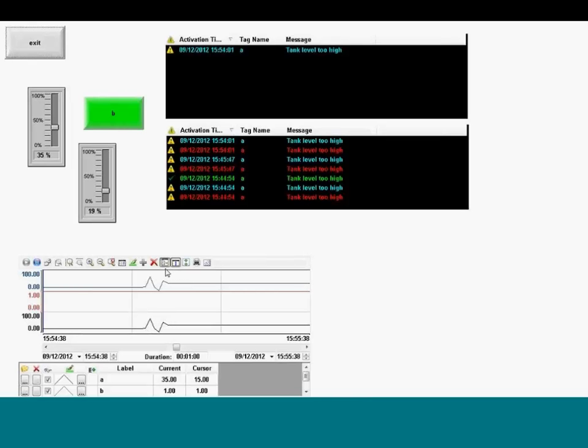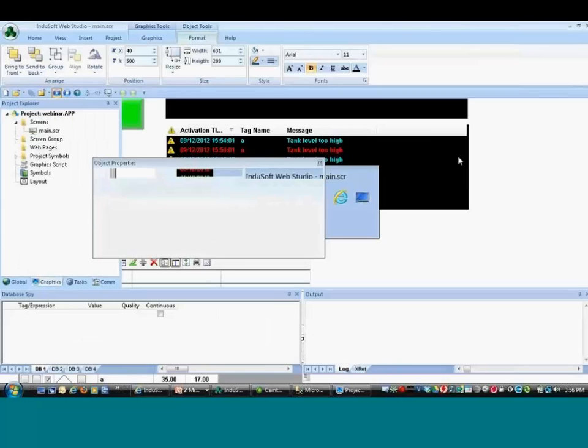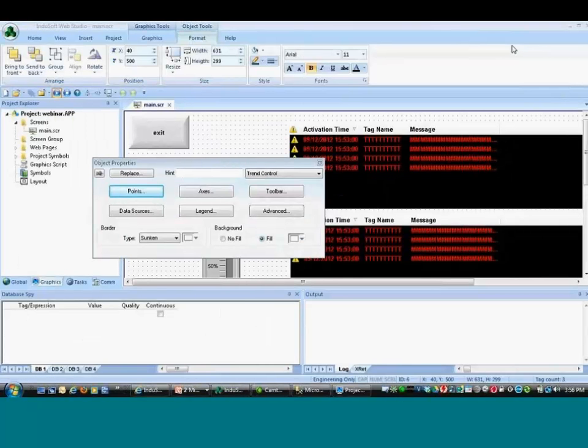you can compare the same variable with different timestamps. So you can visualize, for instance, the level for today and compare how the level changed 1 month ago, or 1 day ago, or 1 week ago. So you can very easily change the offset for 1 pen or a group of pens just by changing the value of 1 tag, using just this offset feature from the point.